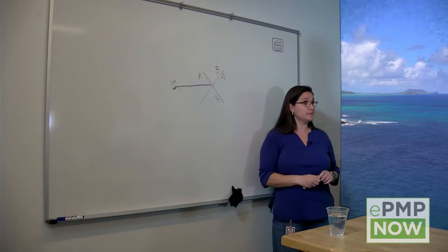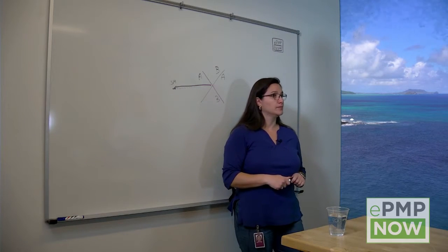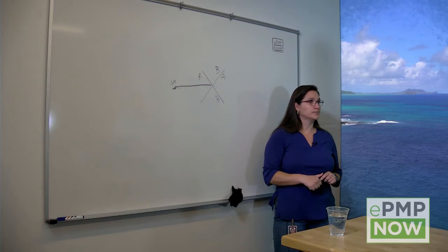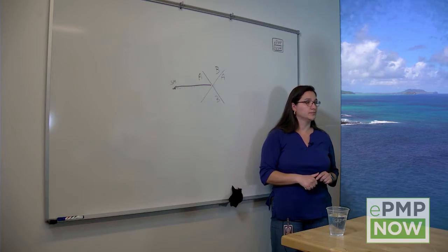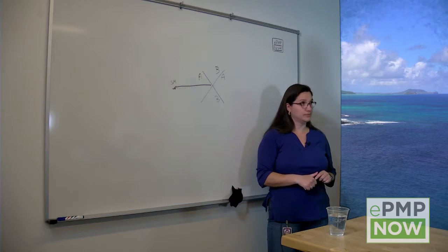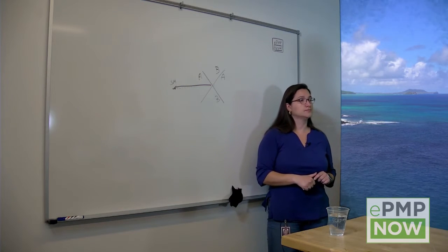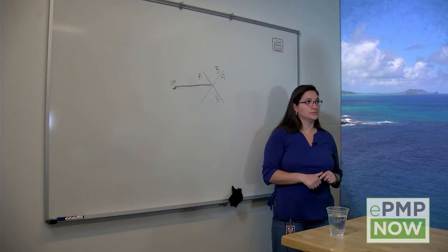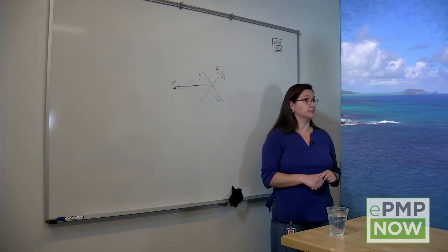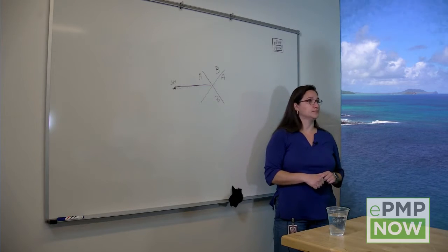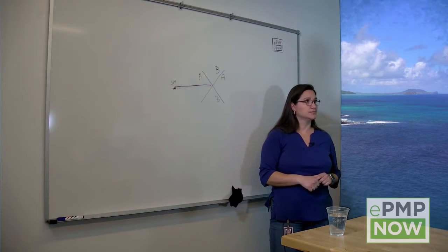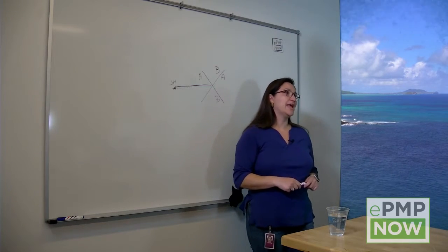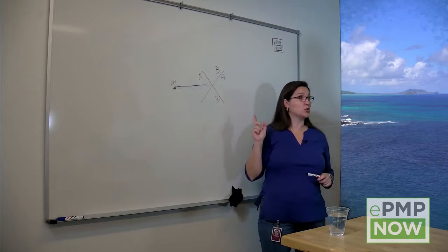So very, very interesting and important point: regardless of external interference, regardless of anything that is not in your control, the simple fact that you have an antenna with poor front to back ratio means a subscriber may not achieve the highest possible modulation, because its noise level is being increased by your own sector using your own frequency, but facing the other direction. Correct. Because it doesn't have good front to back, it's raising the noise floor. And in the downlink direction, this happens all the time.